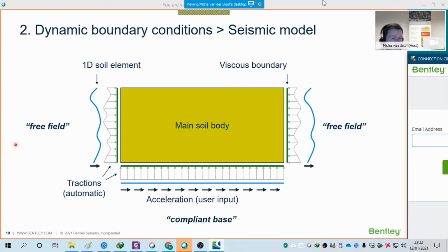But of course, in reality, especially if you look, for instance, at gravels or coarse sands, while having a dynamic analysis, you might still see some kind of consolidation effect for this type of event. If you think about the hydrodynamic time, which is of course a factor of the CV value, but also the time of the loading, even if we have high permeability but very short loading times, we can also see undrained soil behavior in, for instance, sands. And you can see this when we have liquefaction, where you have an accumulation of excess pore pressure in this time.